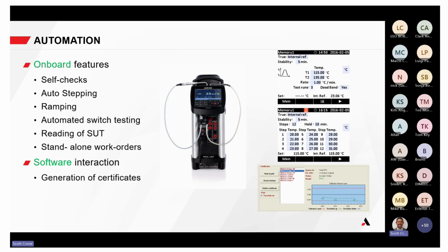RTDs will shift over time. You can actually watch that, and you can do predictive maintenance and say, well, I think this is going to fail within the next 3 months based on what I'm seeing in this indication, so you can prepare for that. All those features make this more valuable than it even was before.